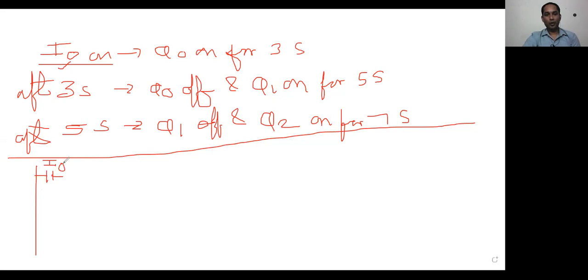And I told, when we have a start signal, we have to latch that with some flag. It's okay. So let me latch it with some flag. M is the flag here. M0, correct? An important thing I told, put this M0 here. It will help you to make the next ladder easily. So M0, tell me what is the next step? M0, Q0, isn't it? It's very clear.